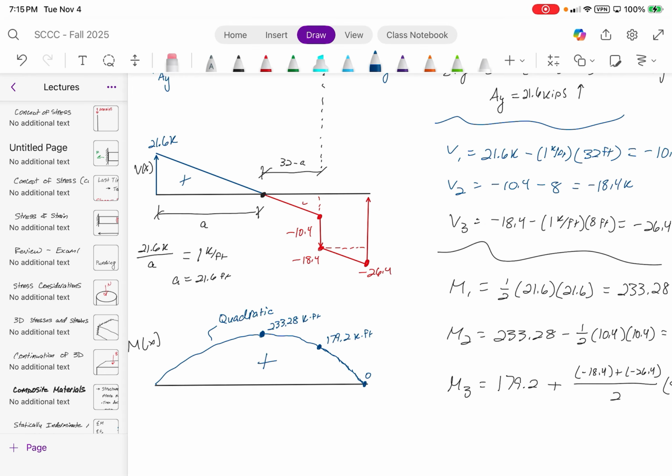I was gonna ask about composites when it comes to that. With composites, you can. I was gonna say, because you have the steel, I'm sure there's some type of W shape inside of it or something like that. Nope, not usually. This is a masonry column, so it's probably just gonna be the CMU blocks that you see with the grout infill, and then probably some type of number 4 rebar with stirrups surrounding it.